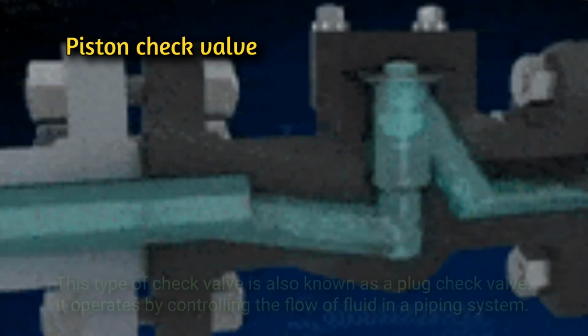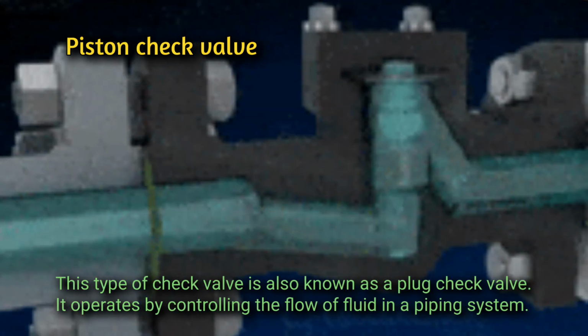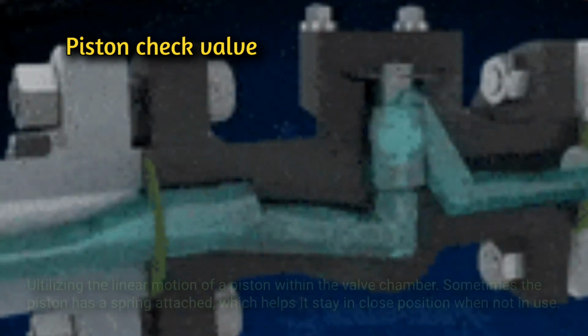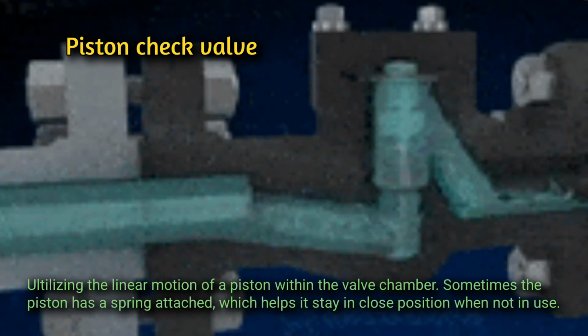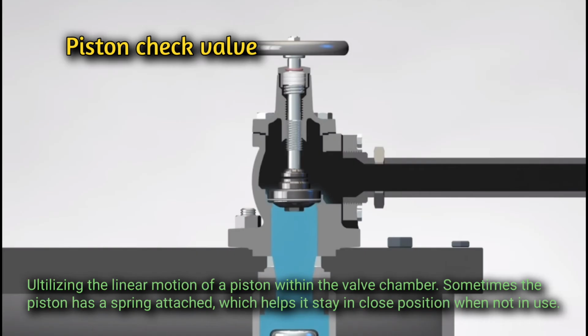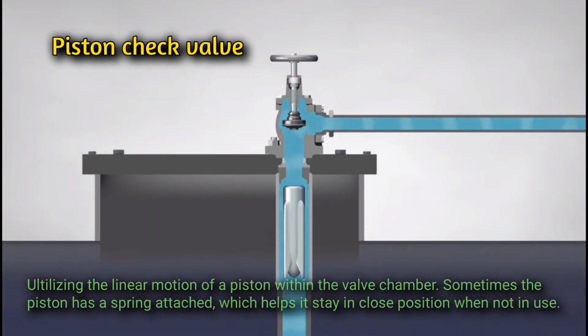Piston check valve. This type of check valve is also known as a plug check valve. It operates by controlling the flow of fluid in a piping system, utilizing the linear motion of a piston within the valve chamber. Sometimes the piston has a spring attached, which helps it stay in the closed position when not in use.